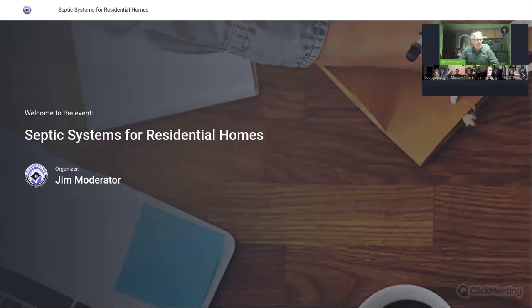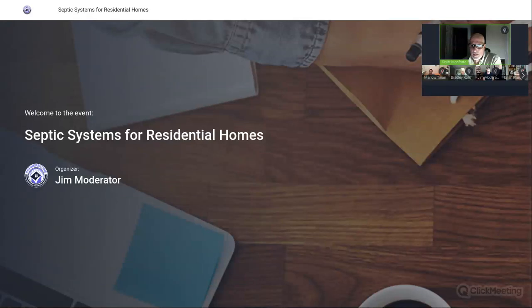Okay. So the next question, Kyle, I can kind of answer it quickly because I have one on mine. I think he wrote condensation line running to the city sewer without water treatment. If it's a high efficiency furnace, boiler, any high efficiency appliance, they're supposed to have a condensate line and a condensate neutralizer on it. And I have them on all of mine. I just put another one on my water heater, my tankless water heater.